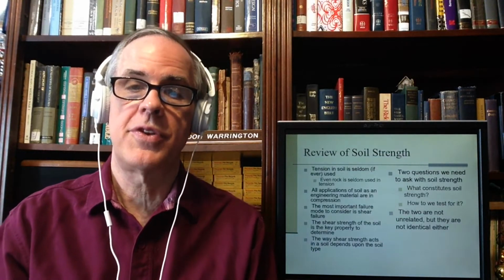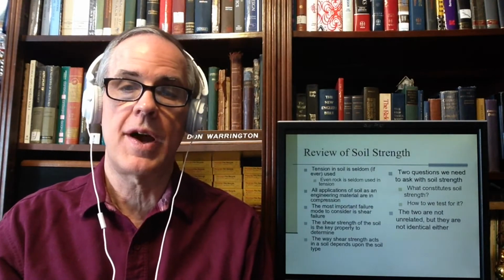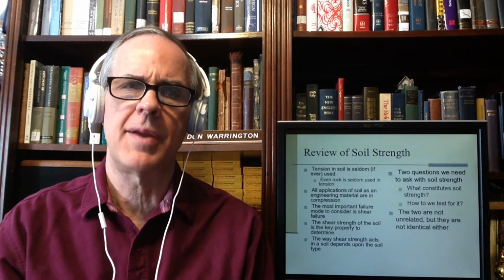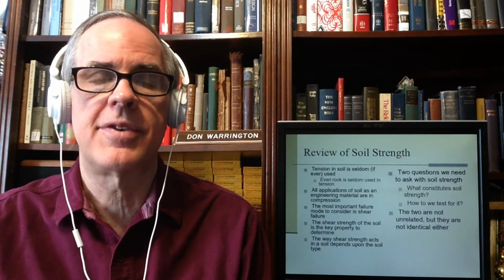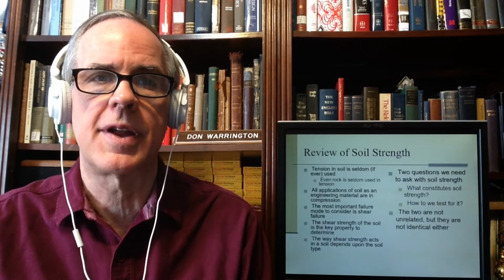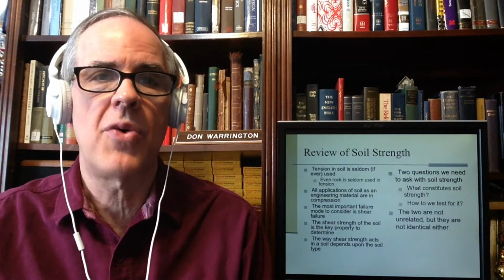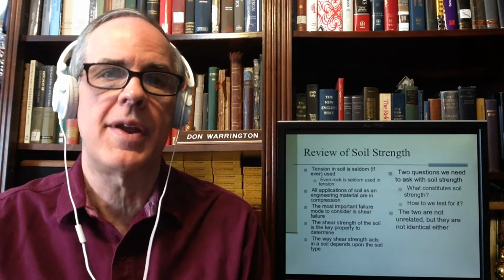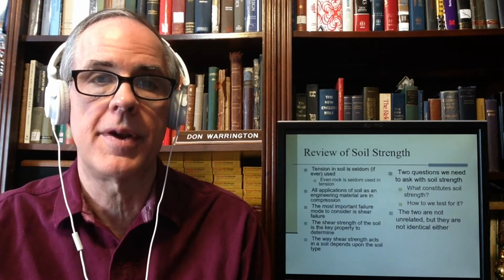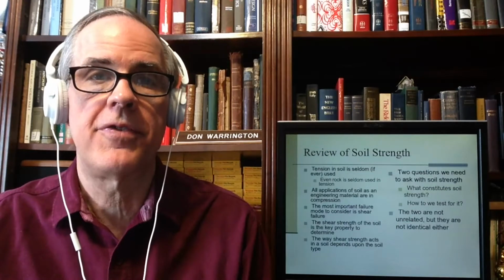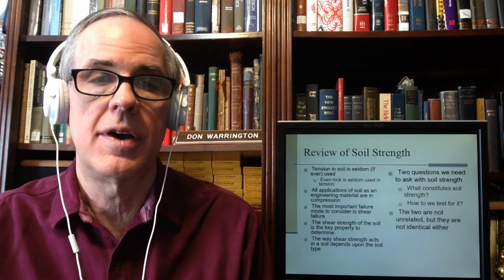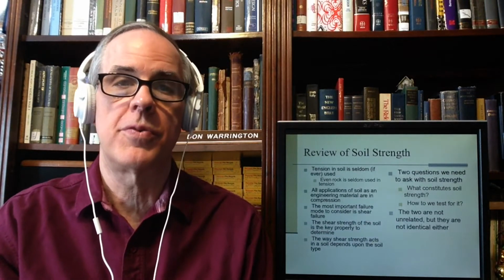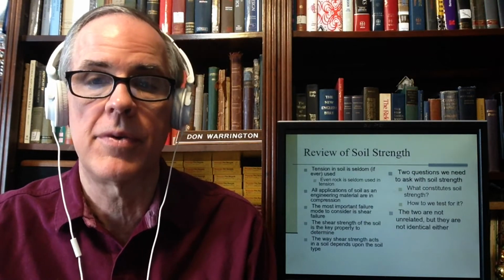Let's review soil strength. Tension in soil is seldom, if ever, used. Even in rocks, we have to be careful about using tension. Sometimes the problem with rocks is different. With soils, actually it's the same problem, but it comes out differently. In soils, we know we have a discontinuous medium going in. We've got a granular medium. With rocks, you've got fissures, which act in pretty much the same way. Fissures don't take tension, just as the voids between soil particles don't take tension either. So we don't do that.